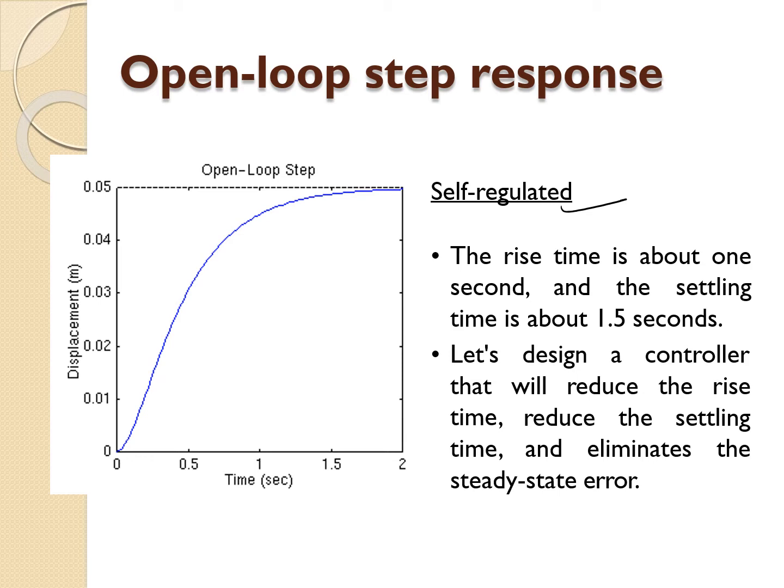Here, the rise time is about 1 second. After this, I will show the graphical figure: what the rise time is, what the settling time is, what the overshoot is, and the steady state error. The settling time is about 1.5 seconds. From this point, the system starts to reach its constant, which is why we call it the settling time.